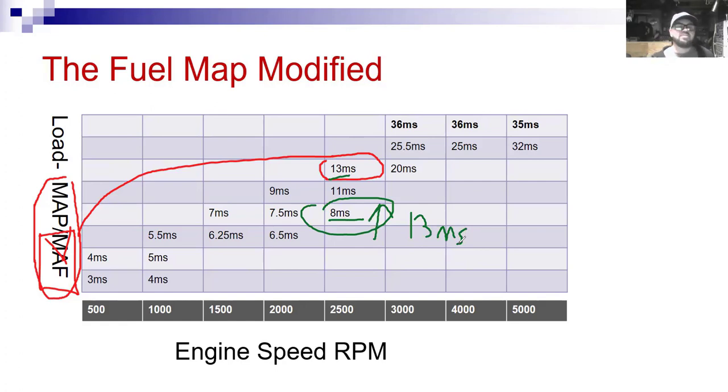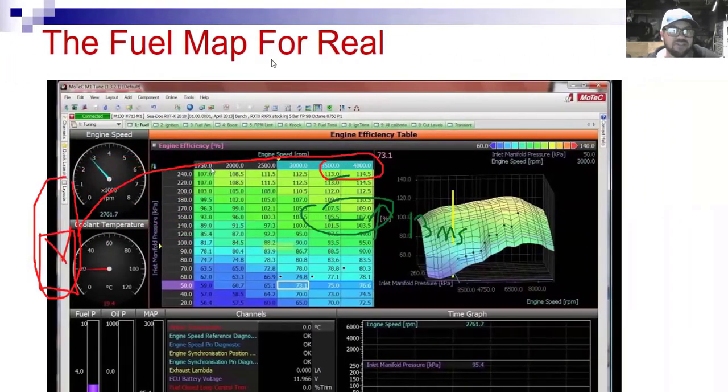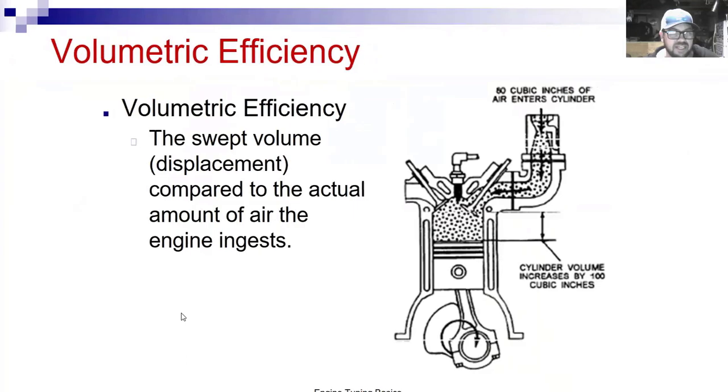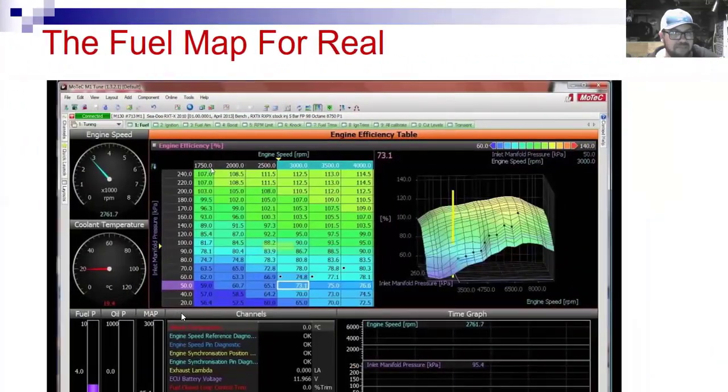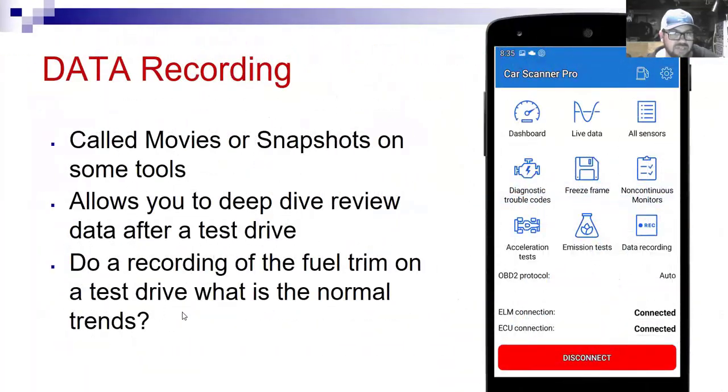He's not setting codes for the mass airflow sensor because, hey, it is still working. It's not like it's open or shorted. It is still working. It's just skewed. It's just off. And so this happens quite a bit. You'll get lean fuel trim codes. It's really a mass airflow sensor. You're not exactly sure. Mass airflow sensors are usually pretty expensive, so I wouldn't want to just throw one on there. And yes, they can be cleaned if you use the appropriate cleaner.